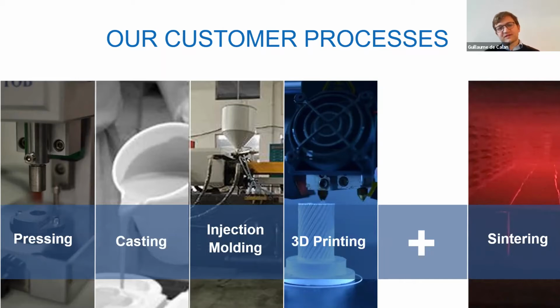And of course, all of these processes are only shaping methods afterwards. In order to have a dense ceramic or a dense metal part, you need to go through a sintering phase, which is a heat treatment at very high temperature.